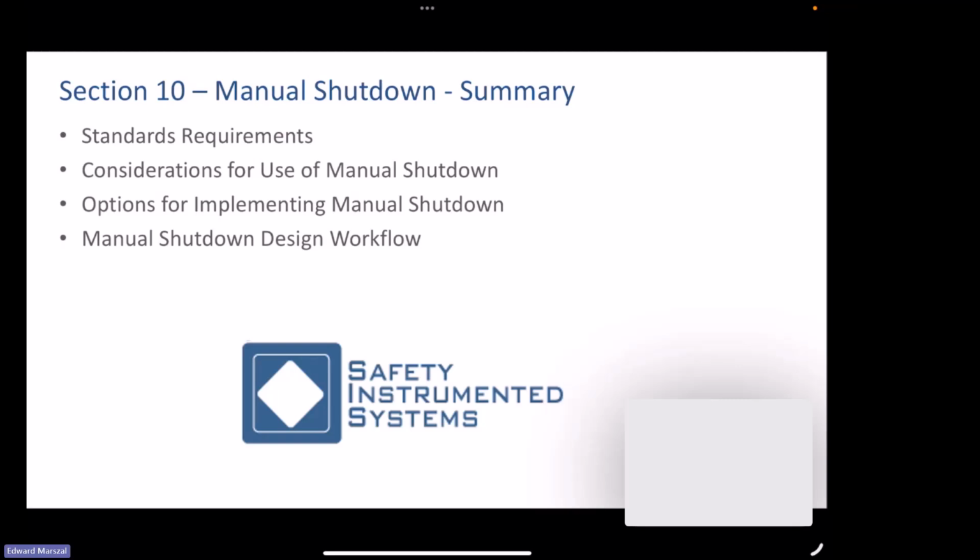A real broad justification is that the dangerous failure rate of a SIL3 certified SIS logic solver is so low that there's no benefit in any manual means of shutdown. I don't know if I would do that if I owned the plant, but if somebody made that case to me, I could not disagree with it. You're basically backing up something that has essentially zero probability of failing.